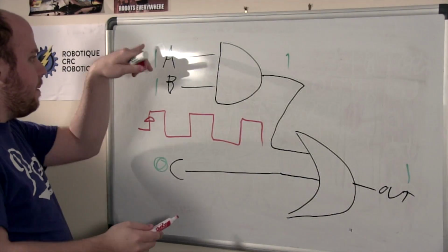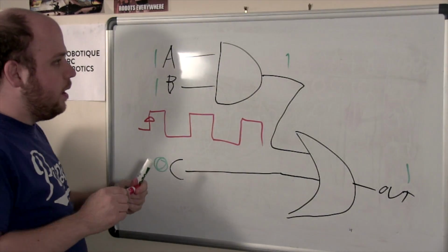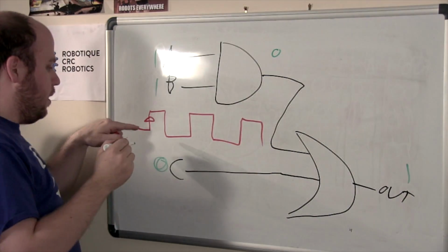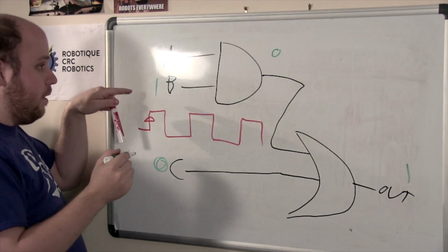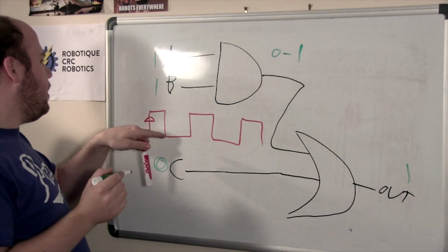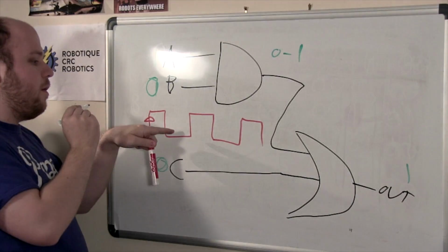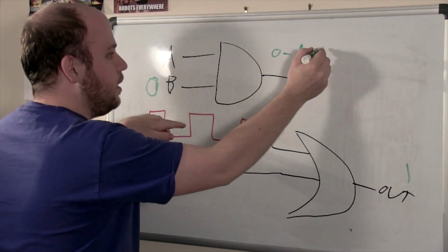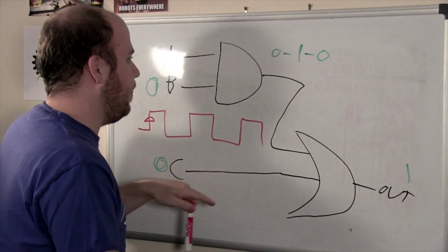So for example, if I put 1,1 over there, initially the output is at 0 because it didn't get computed. Then first clock, it's up, I got my 1, my output. Let's say that in between we switch it to a 0. Then there's a new rising clock, then the output will be 0, and so on and so forth.